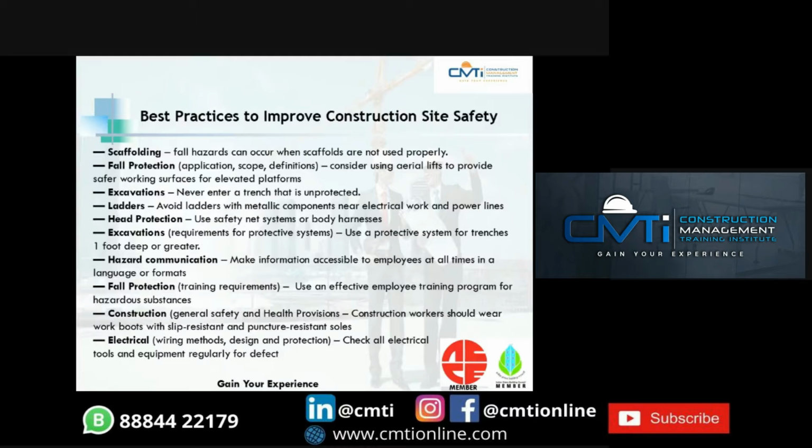Next is the head protection. Use safety net systems or body harness. Next is the excavations requirements for protective systems. Use a protective system for trenches 1 foot deep or greater. And further is the hazard communication. To make information accessible to employees at all times in a language or format they understand.